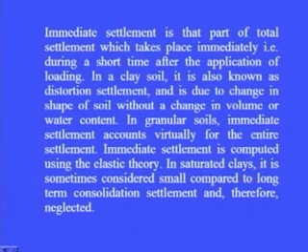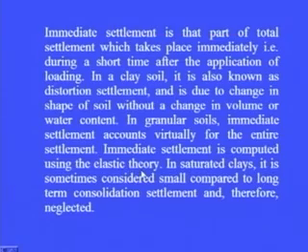In granular soils, immediate settlement accounts virtually for the entire settlement. There is very little consolidation settlement. Immediate settlement is computed using the elastic theory. In saturated clays, it is sometimes considered small compared to long term consolidation settlement and therefore neglected.